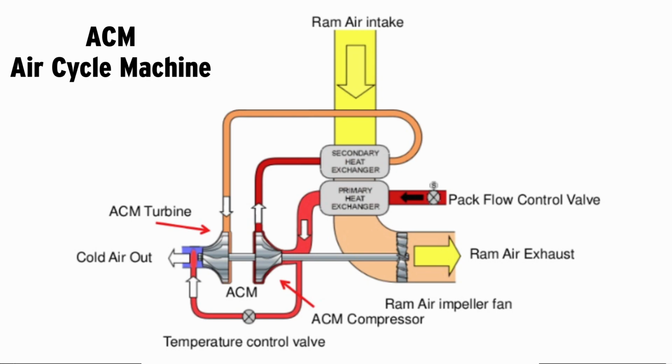So it's going to spin. So remember how a jet engine works: once it ignites that fuel-air mixture, that hot gas is rushing out the back so fast that it hits the high pressure and low pressure turbines, and it runs those high pressure and low pressure compressor spools. So the engine itself, some of that energy that's not used for thrust is actually running those compressors. The same thing happens here.